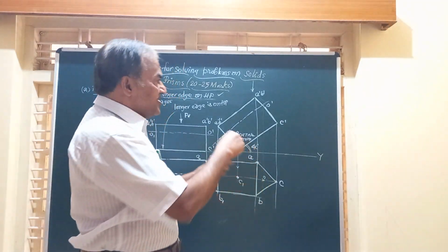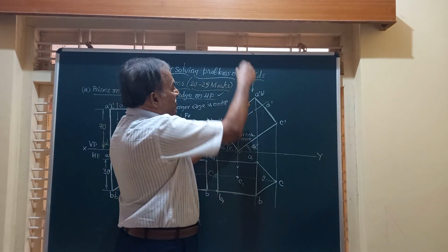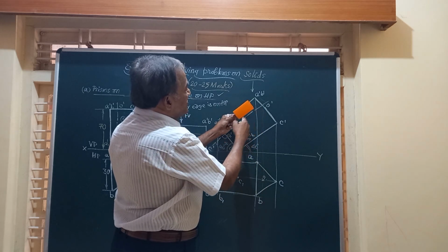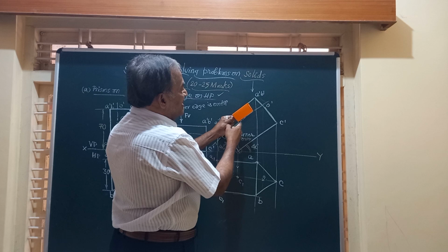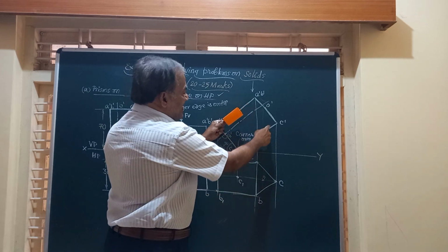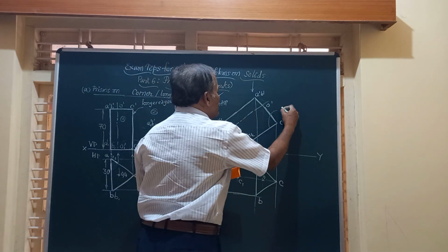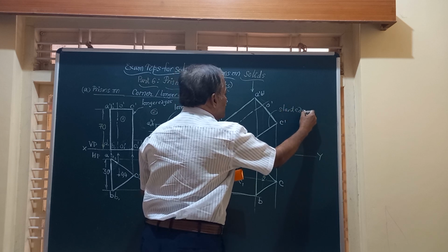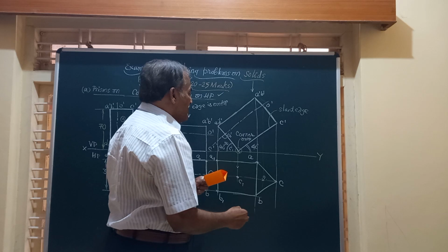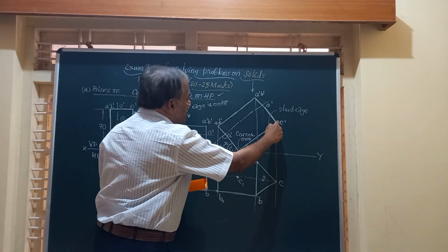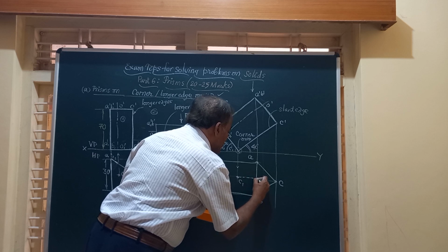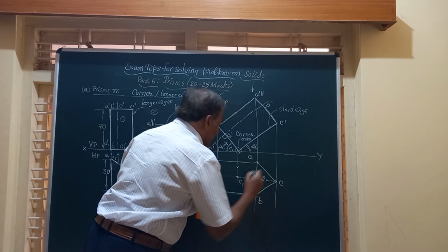When you are looking at this object from the top view, it is exactly similar to this. You are not able to see this corner and also that slant edge. This slant edge is here now. This slant edge is not visible to the observer in the top view. Hence, that particular edge CC1 is to be joined by an invisible line, a dotted line.